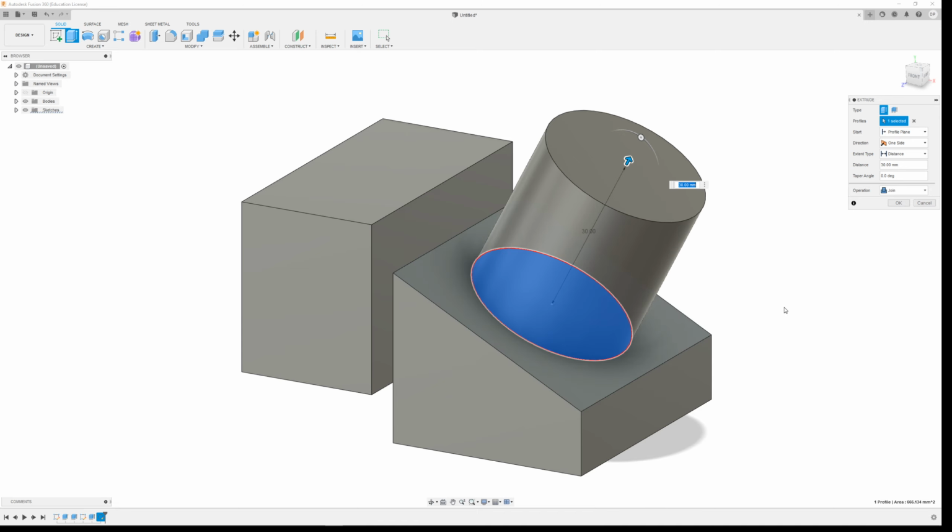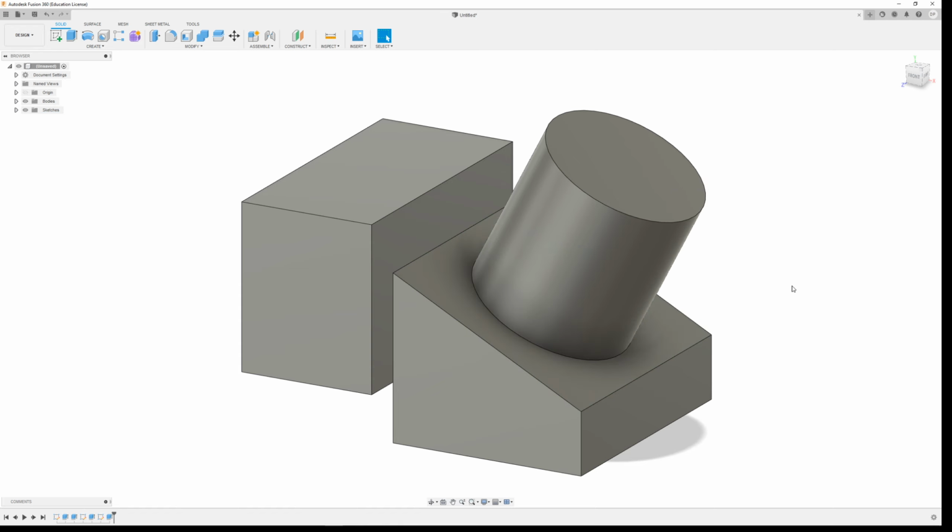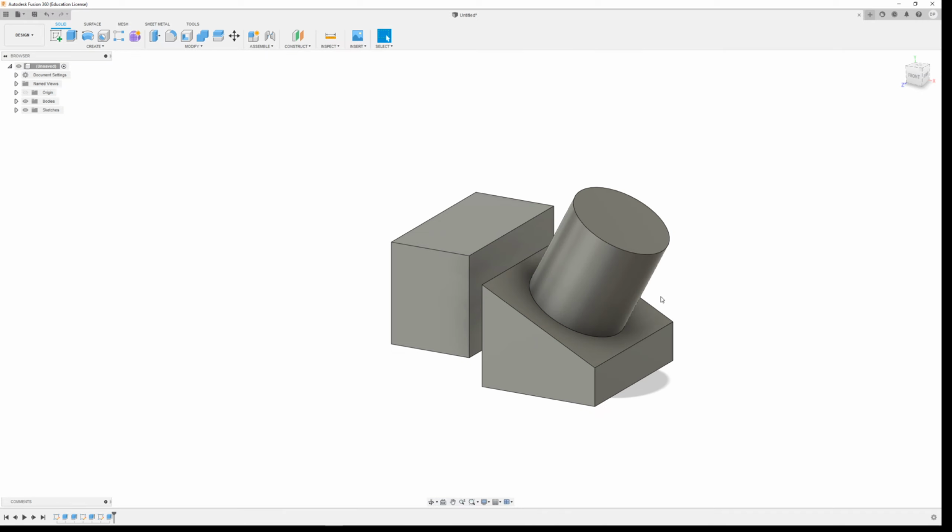So before we can extrude, you've seen in tutorials before that the surface has to be flat. It has to be a representation of a Cartesian plane, which the basic Cartesian planes are x, y, x, z, and z, y. But a Cartesian plane is any sort of flat surface in the x, y, z coordinates. And so here you have a flat surface, so we can extrude this circle out of it. And it's always coming out at a perpendicular.